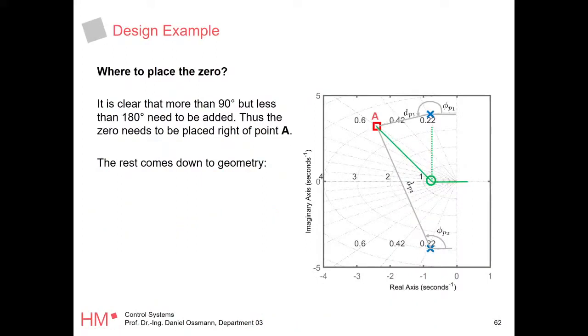This is a picture now. We decided for the 0, right? Because we said the 0 will add us some angle in the angle criterion, and we are missing this 126. So the question is where to put the 0. What happens if I place it here? The angle I'm getting is smaller than 90 degrees, because if I move further in this direction, it will actually get smaller.